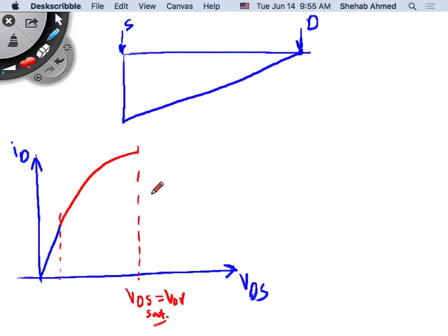Yeah, because you saw this in the textbook. The area is not changing, so I agree. So the relationship between ID and VD is no longer governed by this quadratic anymore. There's no change in area at all. So you increase VDS, area is not changing. Area of the channel is not changing. Khalas, you've pinched it. But what happens to the channel?